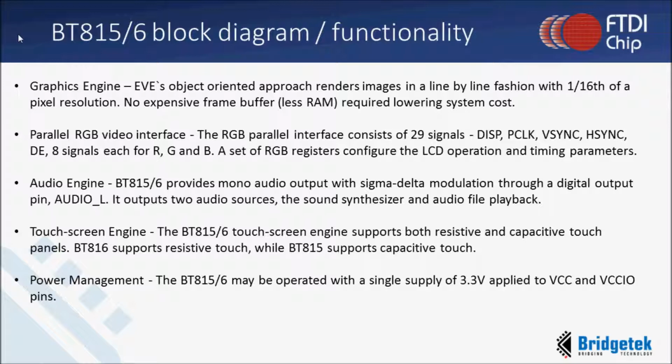Next we have our touch engine. This touch engine supports both resistive and capacitive touch panels. The BT816 supports resistive touch, while the BT815 supports capacitive touch. Power management on the BT815/6 is operated with a single supply of 3V3 applied to the VCC and VCC-IO pins.